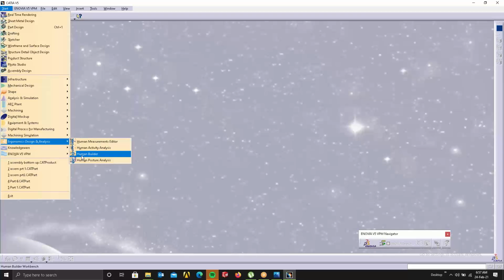After you put this ergonomics model there, you'll see that the seat is covering only a small section of his backside. So what you do is increase the length a little more, like 50 or 80 mm. Only so much you will increase it, and that will enhance the design, and he'll have a comfortable sitting position. So you'll know exactly how much material to be added. You don't have to add more than required or less than required.